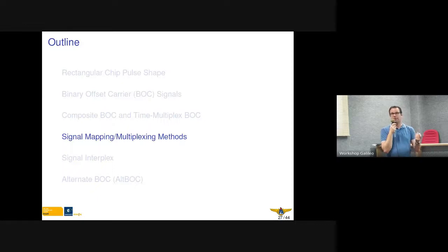So, in my opinion, we are moving towards an interference limited case now, because all the systems are ramping up the power. They are discussing in their modernizations and evolutions to increase the power on the satellite payloads. So we are moving towards this more interference limited case than only being noise limited in the receiver.